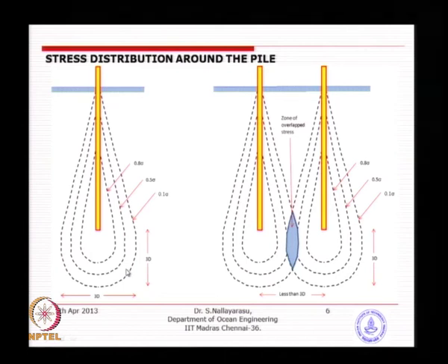So a typical number you can see here, the stress distribution, or we call it the stress bulb at the bottom of the pile, is about 3 to 4 diameters that will be more critical, beyond which it is going to be almost less than 10% of the total stress. So you can see the last diagram, the third one, is less than 10%, whereas in the first one you can see within 3 diameters, 80% of the stresses are dissipated within a smaller distance from the pile surface.